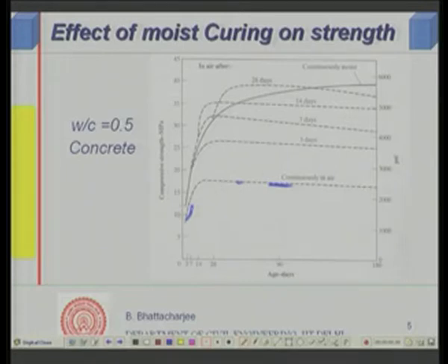Now, you do curing for 3 days. You can see that initially the strength increases up to 7 days, and then some amount of loss would be there, but it would depend on the type of test that was done. In a specific case it is shown that it temporarily increases up to about 14 days, and after that is steady, but it would depend upon the condition of the air, its temperature, relative humidity, whether there is any wind and things like that. In a very dry condition with high temperature, there may be much less reaction, but qualitatively this is fine.